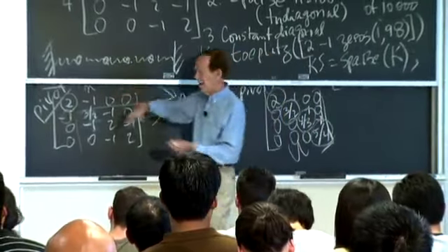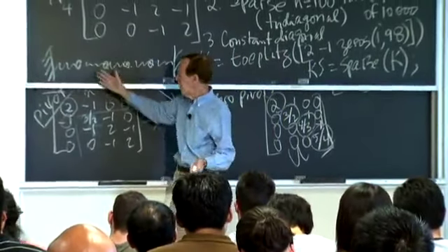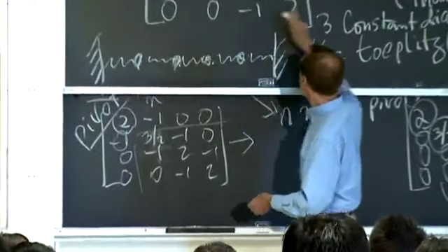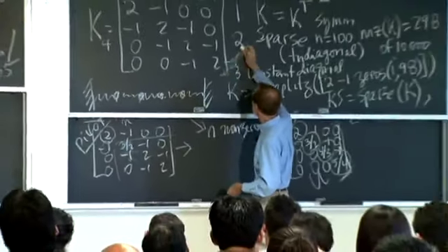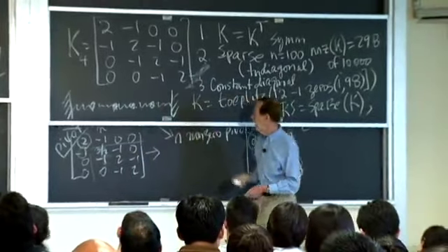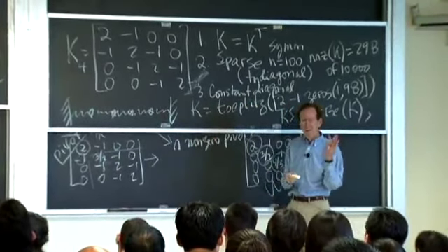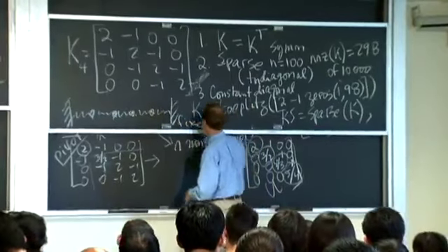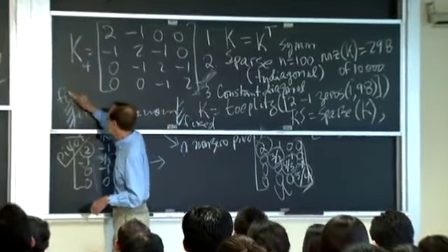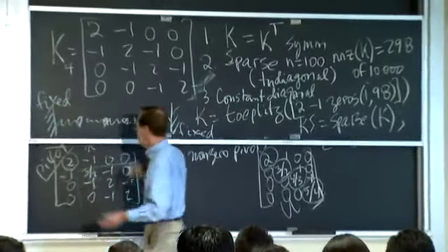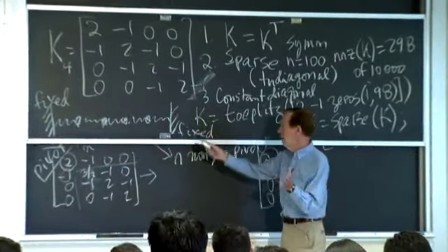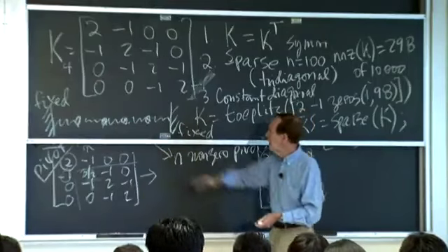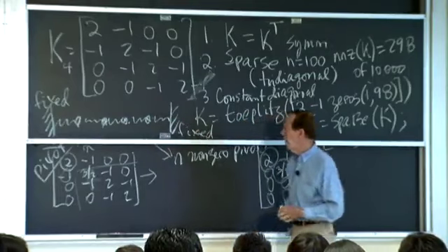Actually, I'll usually draw it vertically. But anyway, it's got 4 masses, and the fact that this -1 here got chopped off, what would I call that end? I'd call that a fixed end. So this is a fixed matrix. Both ends are fixed. And it's the matrix that would govern the springs and masses, and the fact that it's all the same is what tells me that the thing is Toeplitz.